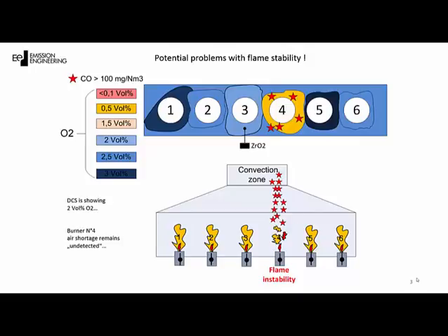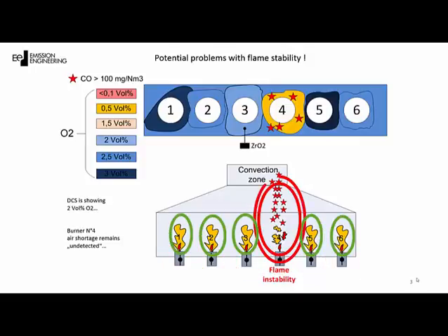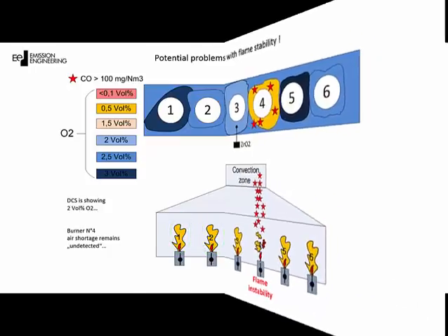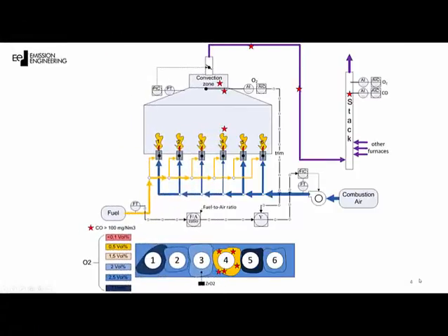What do we do nowadays when oxygen is either too high, or fluctuates, or carbon monoxide emissions are popping up and disappearing? Well, normally, field operators try to readjust the burner air dampers according to either their physical flame observation or their experience of what they need to change in each burner in order to achieve the desired effect. In the example above, let's say that the oxygen analyzer captures a mixture of flue gas from burners 3 and 4.